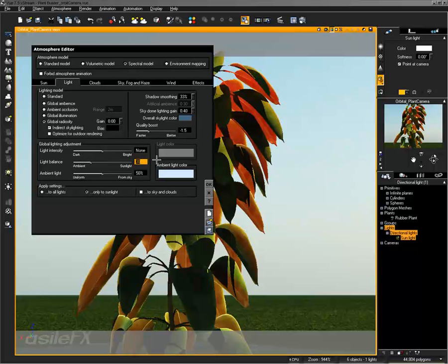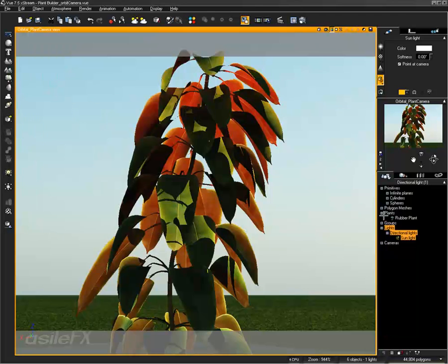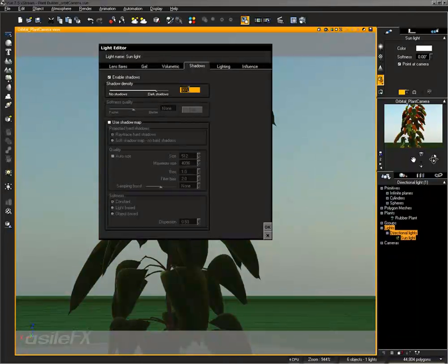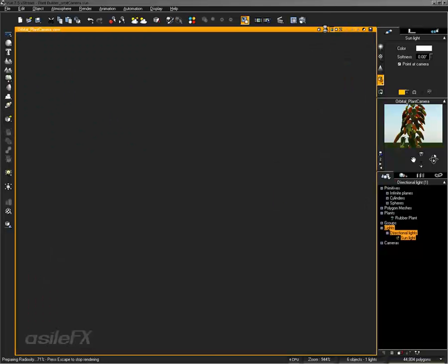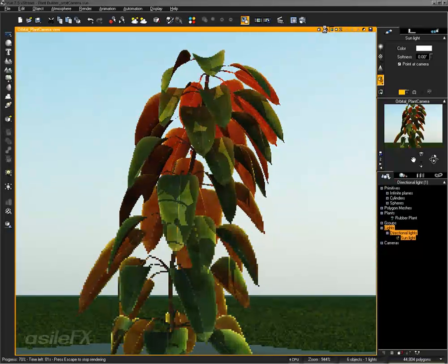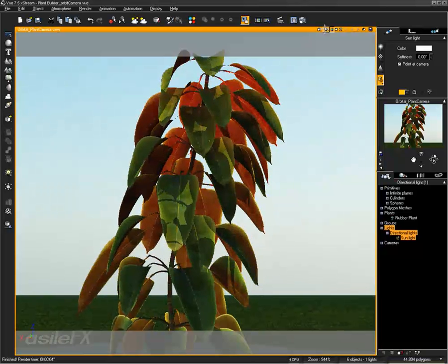So if I was to have an ambient light amount of 30, I could usually get a nice effect by taking the shadow density and setting it to 70. So between those two, we have a total value of 100%. Now, that isn't always going to work for everything, but in a lot of cases when you're using a radiosity render, it does produce a really nice effect.